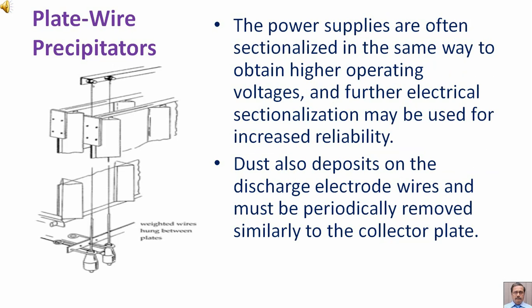The power supplies are often sectionalized in the same way to obtain higher operating voltages, and further electrical sectionalization may be used for increased reliability. Dust also deposits on the discharge electrode wires and must be periodically removed, similarly to the collector plate.